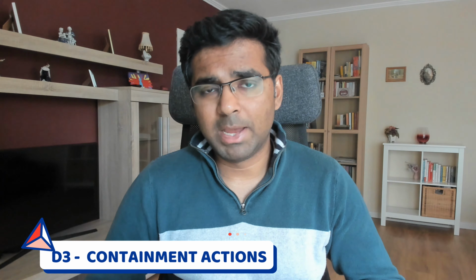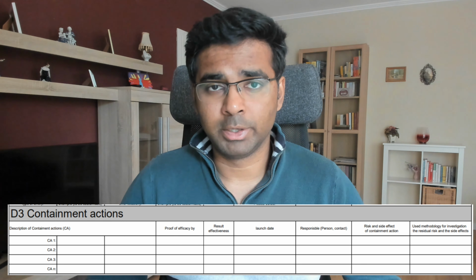Containment is the step where you make sure that no further non-conforming parts go to production. It means if there are bad parts at your customer side, your side or at your supplier side, you need to immediately block the suspect parts and make a sorting activity within 24 hours of the notification of the claim.